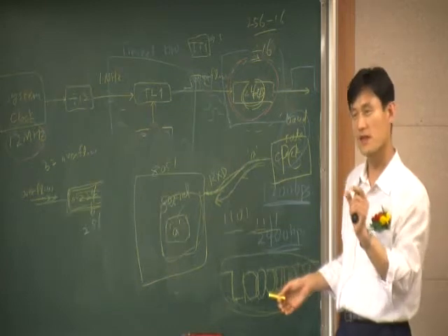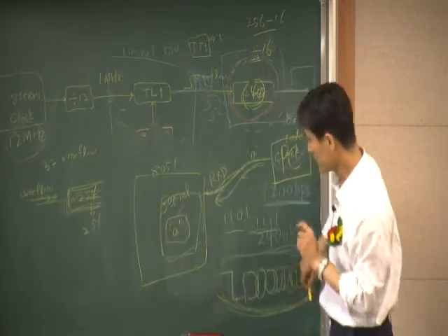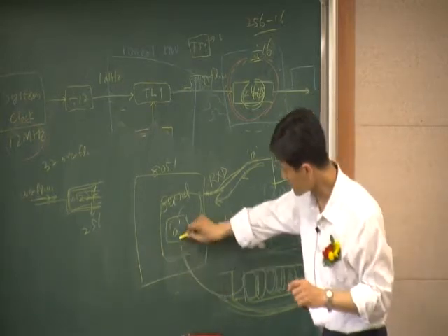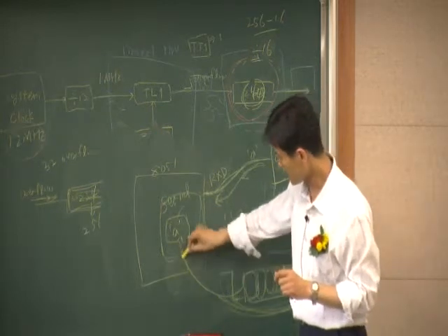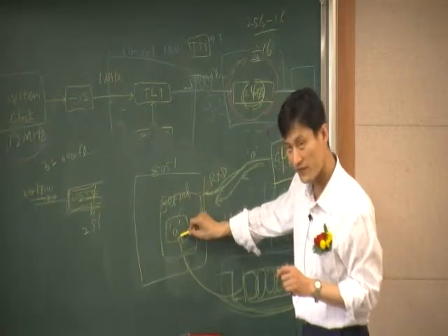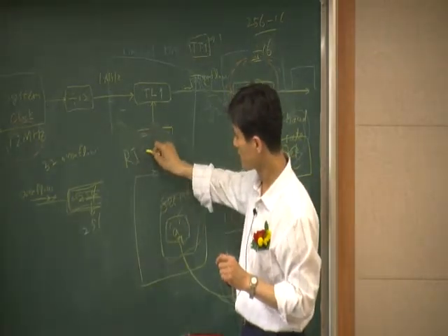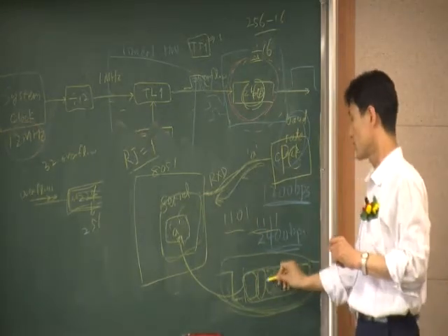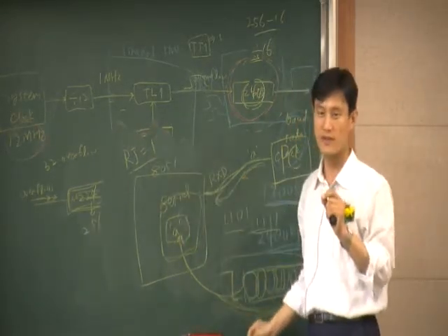And once this decoding is all done, then these 8 bits go to SBUF. Once these 8 bits successfully go into SBUF, then the RI bit becomes 1.